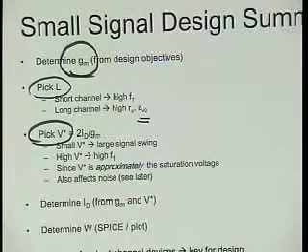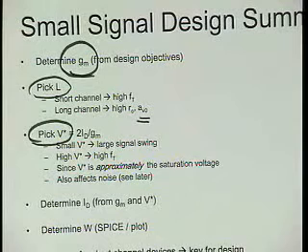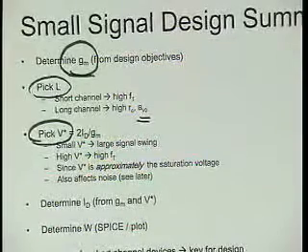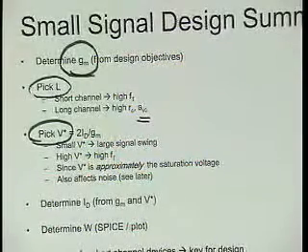We also have to pick a V star. And there again, we know that it's not going to be 5 volts. It would be impossible. So a few hundred millivolts is good. And heck, if we really need efficiency, speed isn't that important, and low power is the name of the game, then maybe we can get by with 120 millivolts. Don't make it 50 millivolts, because the transistor is going to work very inefficiently, if you even can get it there.